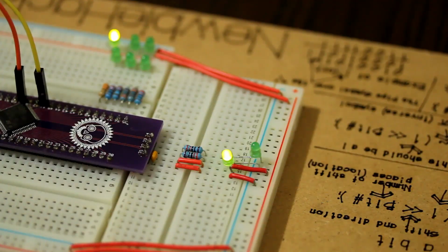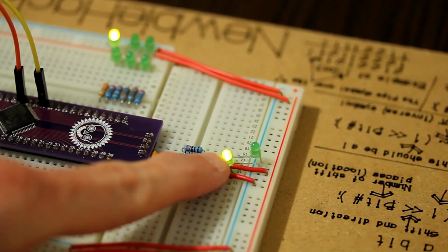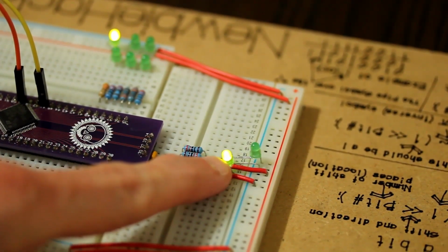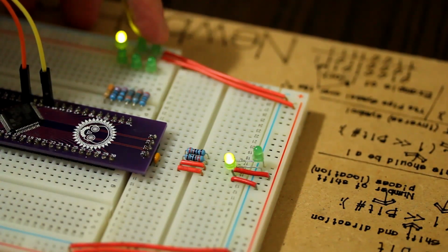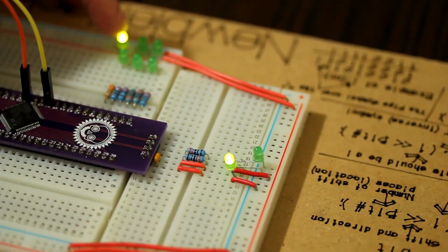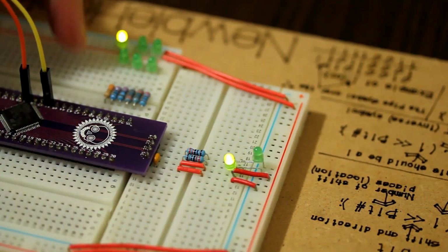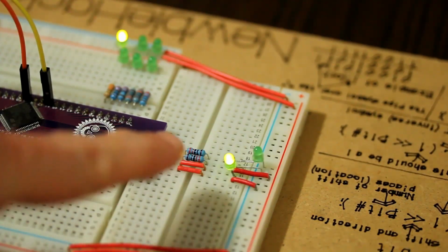Okay, the microcontroller was programmed, and you can see that bit 0, the first position, is a 1 like we would expect. And then the second, third, fourth, fifth, sixth, those are all zeros, which is correct. And then the second to the last one, or the 7th position, is a 1, and then the 8th position is a 0. So this shows the letter A correctly in binary format on the LEDs.